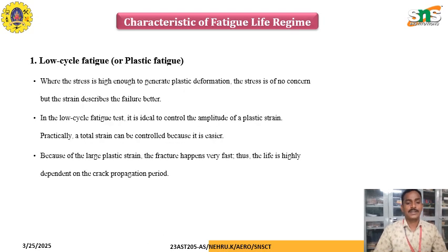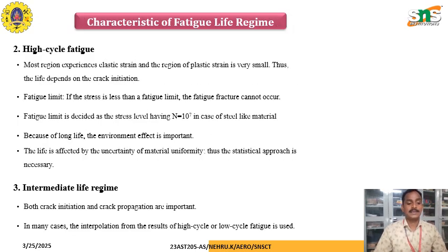The characteristics of fatigue life regions. Low cycle fatigue is fatigue due to plastic deformation. When the stress is high enough to generate plastic deformation, the stress is of no concern, but the strain describes the failure better. In a low cycle fatigue test, it is ideal to control the amplitude of the plastic strain. Particularly, the total strain can be controlled because it is easier. Because of the large plastic strain, fracture happens very fast, thus the life highly depends on the crack propagation period.